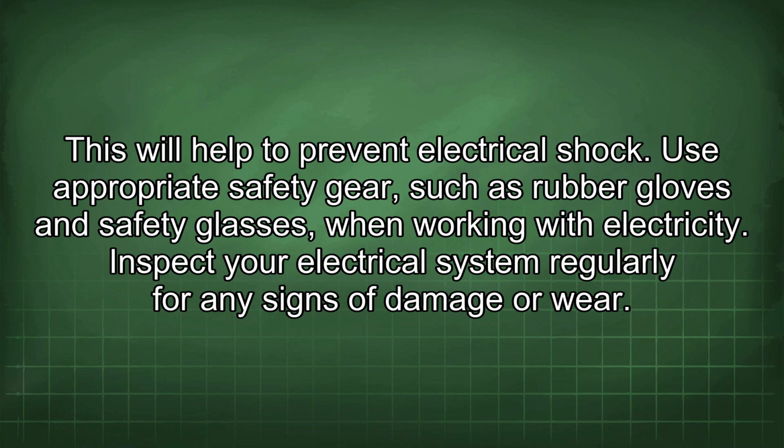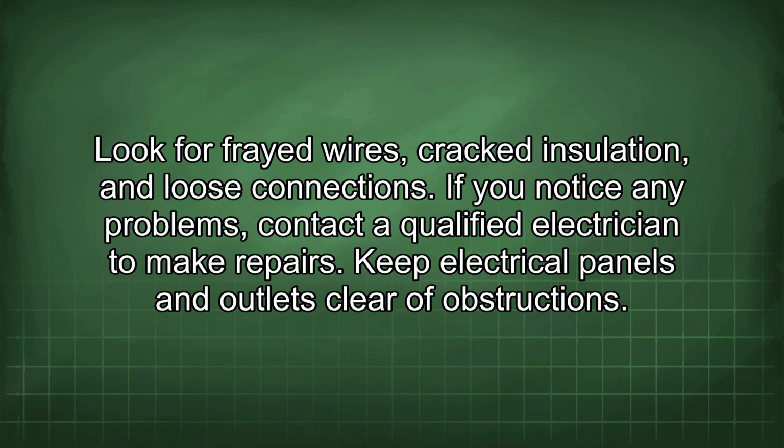Inspect your electrical system regularly for any signs of damage or wear. Look for frayed wires, cracked insulation, and loose connections. If you notice any problems, contact a qualified electrician to make repairs.